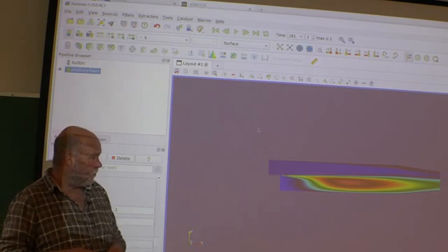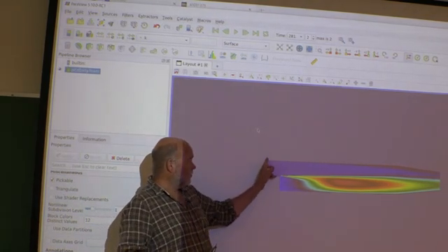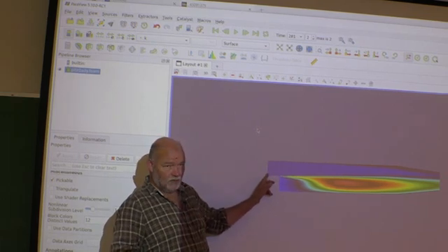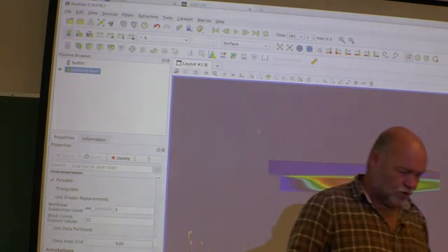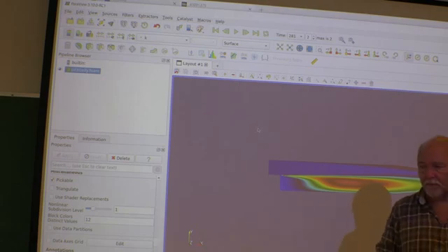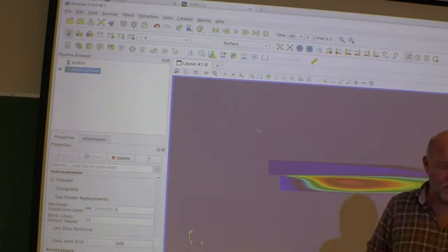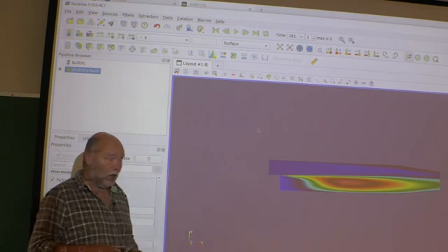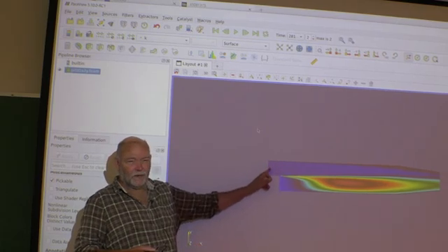So that's not good. One important thing here, we are sending in something here at the inlet. Have a look at that later. We have to give a value for K. Now, there you have to sort of find an estimate for what that number should be. And yeah, you find several recipes for this, either in the user guide in OpenFOAM or the Turbulence file I gave you last time. It should be out on the homepage. So you can find a way to calculate or give an estimate of this K here.